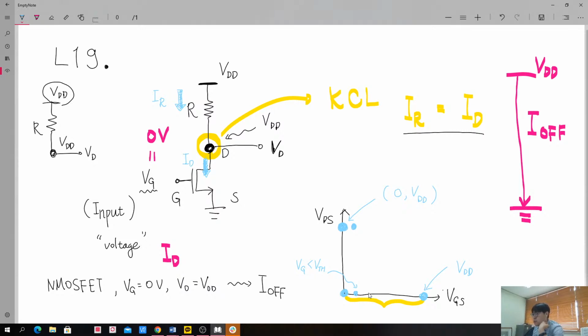Then let's go to certain voltage. For example, I will just use this one as a threshold voltage of this system. So let's say that this is corresponding to our VTH. So this curve will be almost flat until the gate bias reaches to what? To VTH.